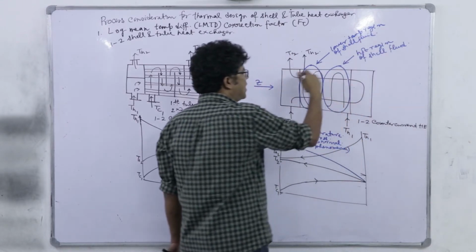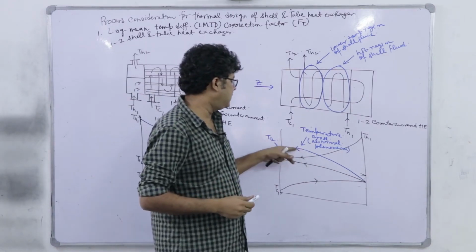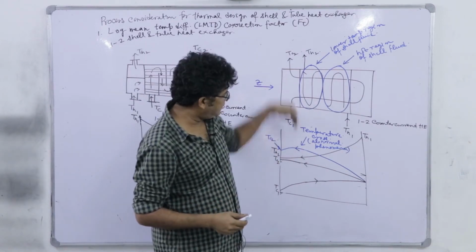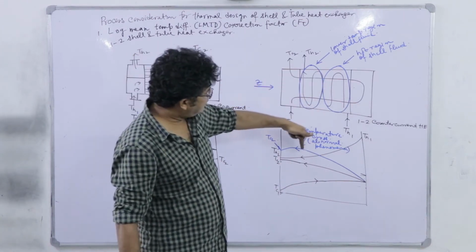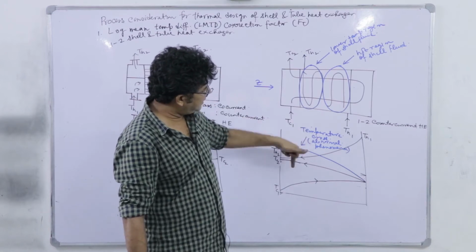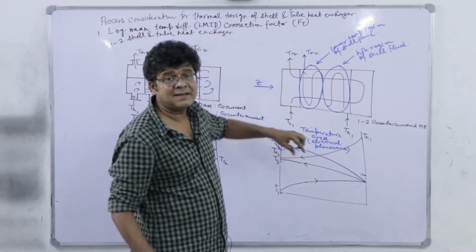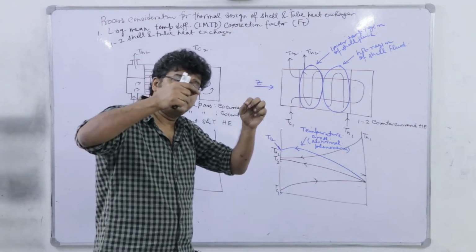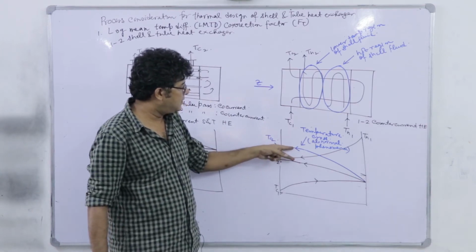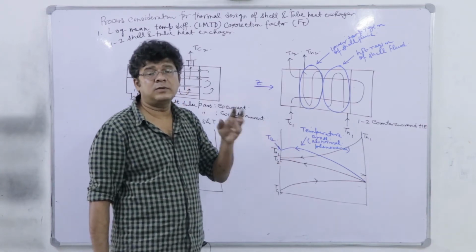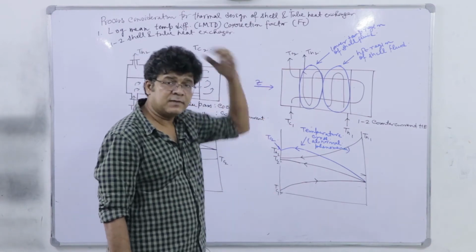right, locally the cold fluid temperature may be higher, it exceeds, and once it exceeds, the direction of heat transfer changes. So, now the cold fluid in this region is delivering heat to the hot fluid, and definitely we will have a maxima, because it shoots up, attains a maxima and then decreases, and the maxima is never going to take place at the outlet, because the direction of heat transfer changes.